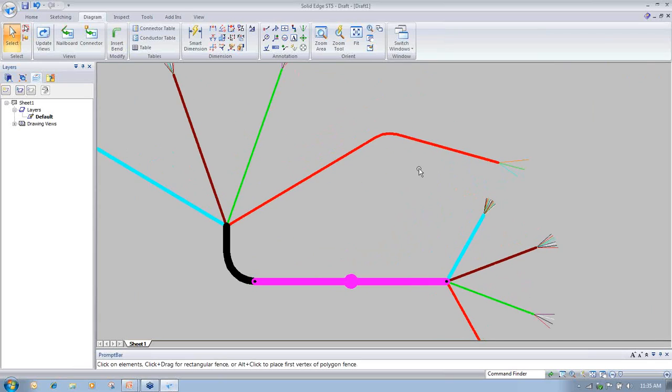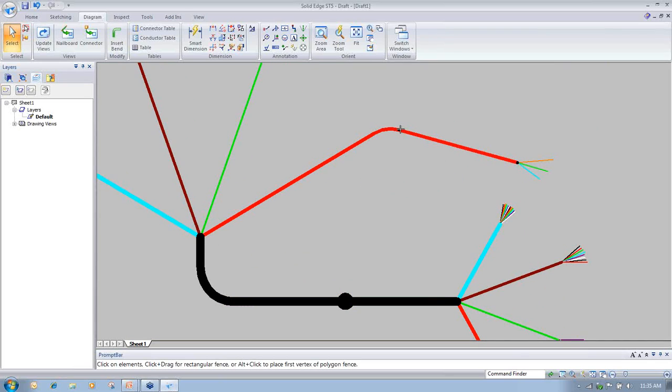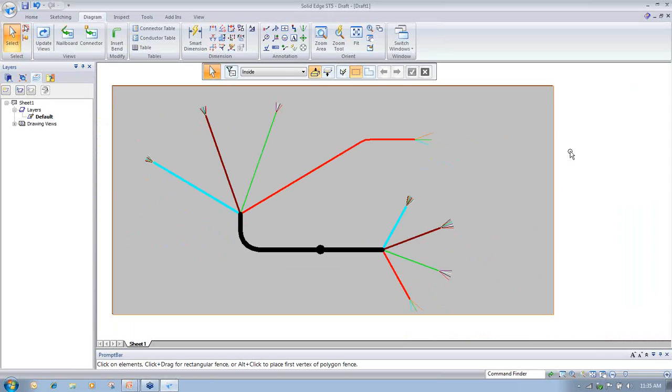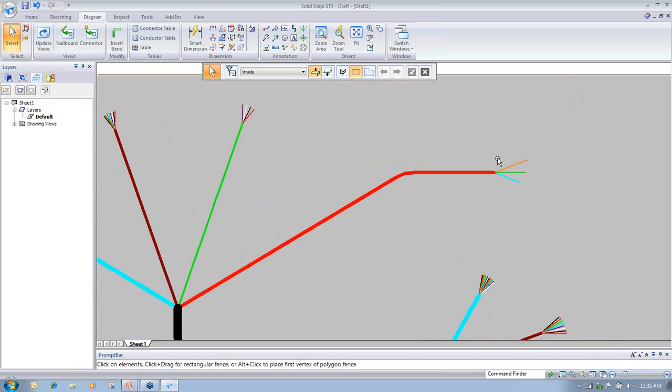But the cool thing is once you get a bend in there, simply by selecting the wire itself, you can manipulate the rotation of the bend and also the location of the bend, again maintaining the length of the wire harness based on the harness created in the assembly environment. So we're able to already bring in the wire harness. We have it flattened, everything's set up, and we're ready to start working through actually setting this thing up through the nail board and getting some things established.